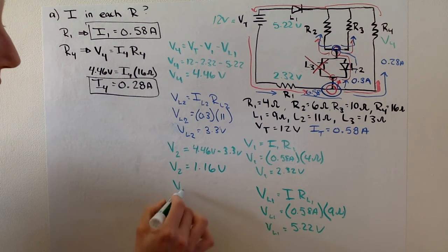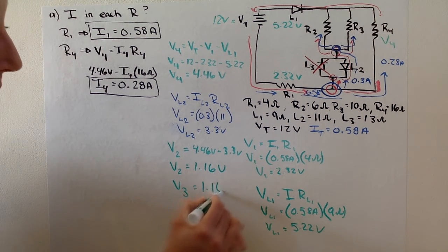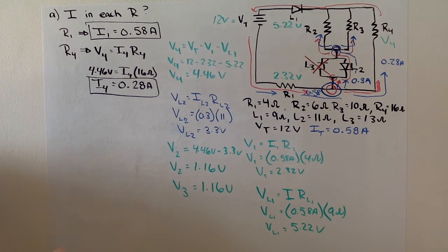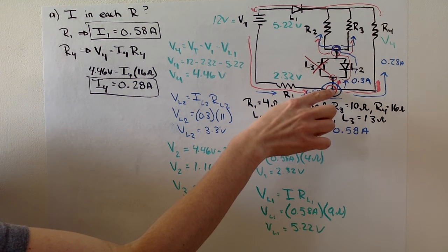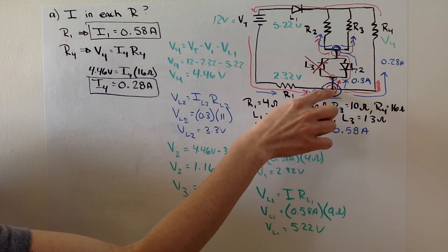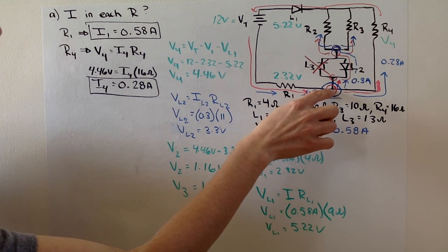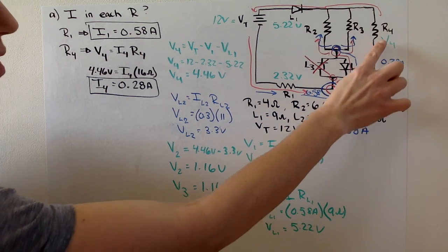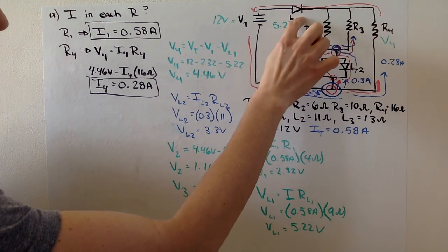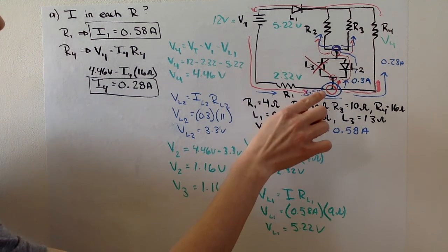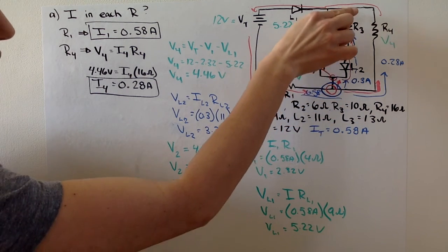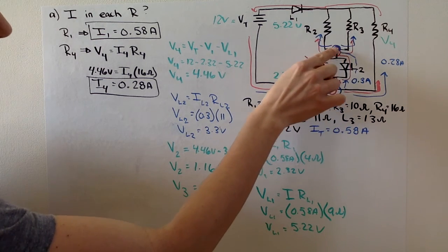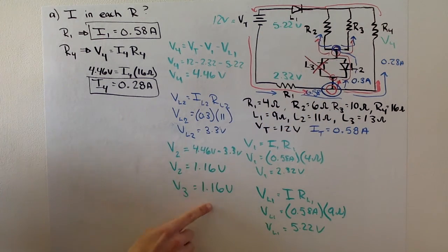And this will also be the voltage drop over resistor 3. Again, when current splits, it has a certain potential left. All of that gets used in R4 before it goes through LED 1, so all of that same potential has to get used through LED 2 and R3, or through LED 2 and R2. That's how I'm able to figure these out.